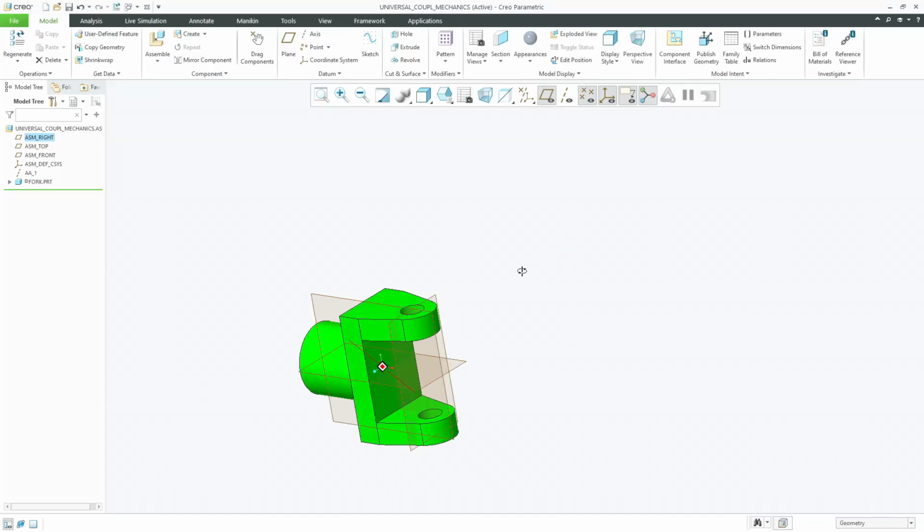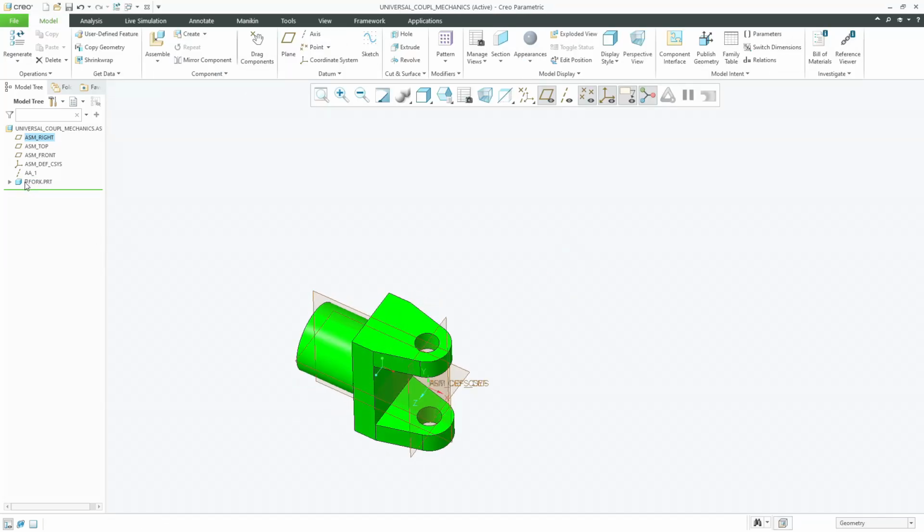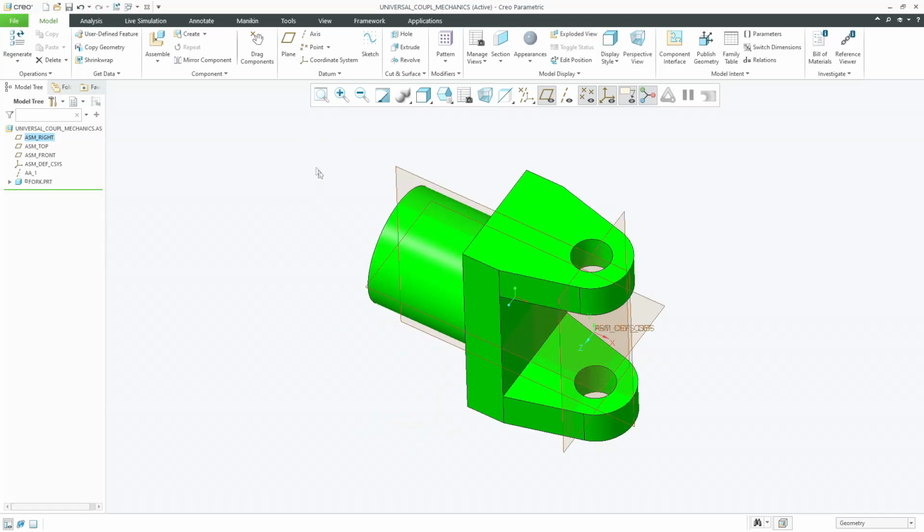Here you can see a box next to the fork name, which means this connection has not been made as a rigid connection, and it is also not an undefined constraint. So there is a box with a dot in the middle which defines that this is made with some other special connections.